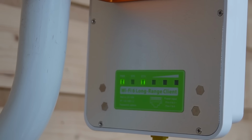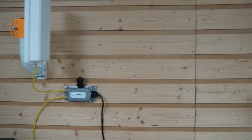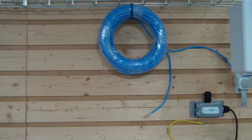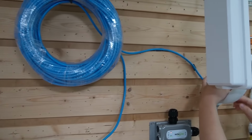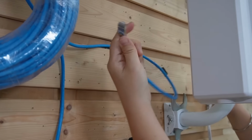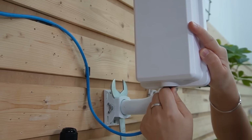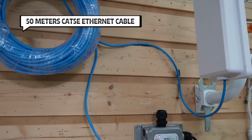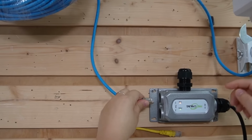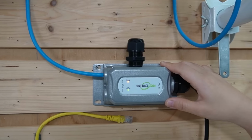So the injector powers the first bridge, which shoots the signal 15 kilometers up to the second bridge. That second bridge receives the signal, but it also needs power. So we are using an Ethernet cable here, connect our wireless bridge. This is a 50 meter Ethernet cable connected directly to another passive PoE injector.